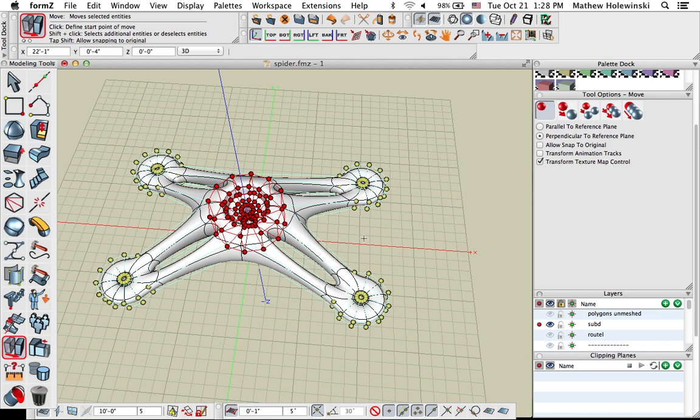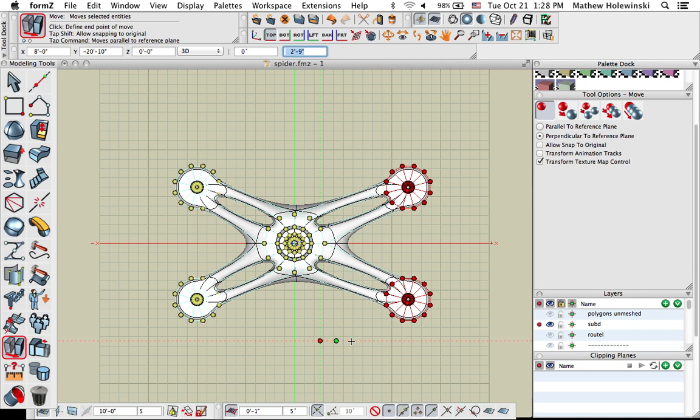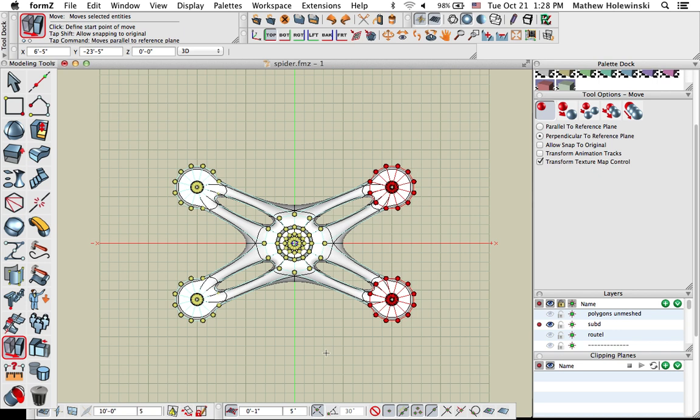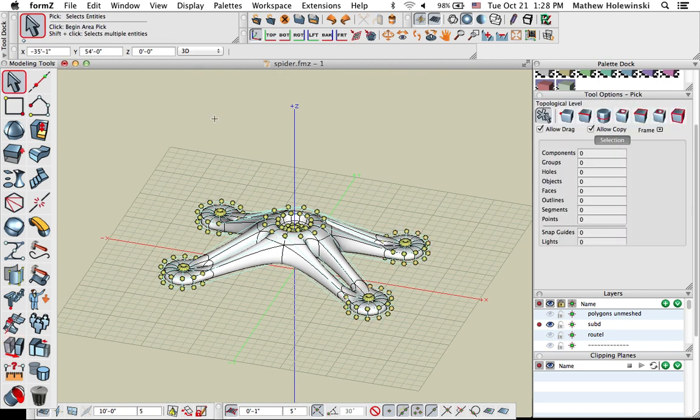All right, let's say we want to change the position of the hole openings. Well, go into a top view. Let's say we want to extend this out a little further. We can grab all those, and I think at this point you're getting the idea of how playful these subdivision objects are. All right, but the next step is, how do we get more machine type detail into this? Let's take it to the next level. I want accurate holes, accurate counterbore holes. I need to do some Boolean operations to machine out all of this more detailed stuff.